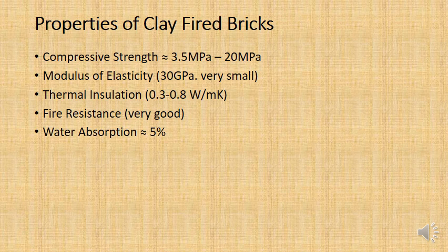So, yeah, clay-fired bricks. I think that you should be using clay-fired bricks for a lot more of your buildings here in Kurdistan, personally, because of thermal insulation and a few other reasons. The downside, though, is they're a lot more expensive. I think for every concrete block you buy, it costs about 250 dinar.